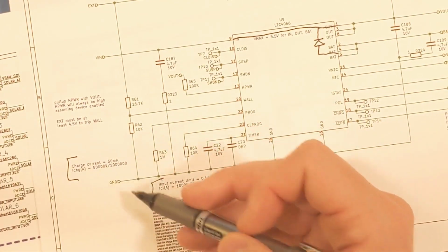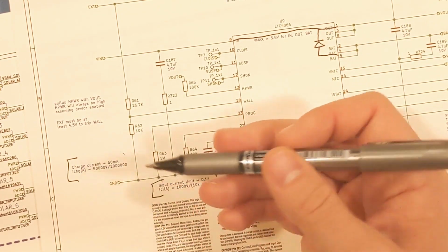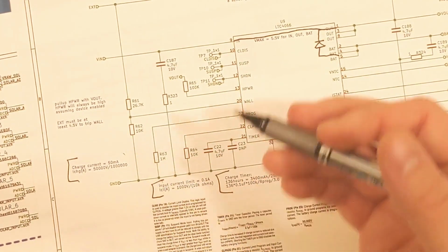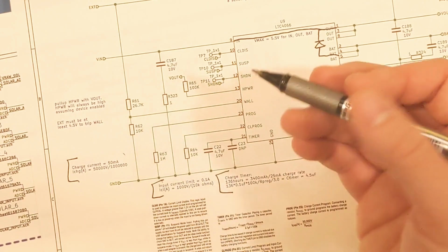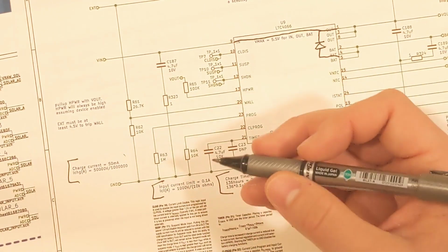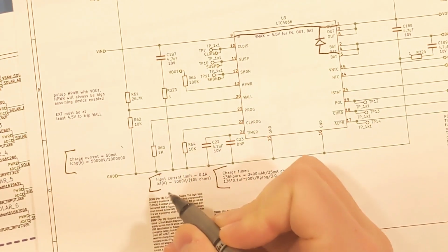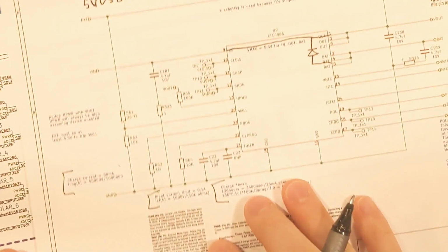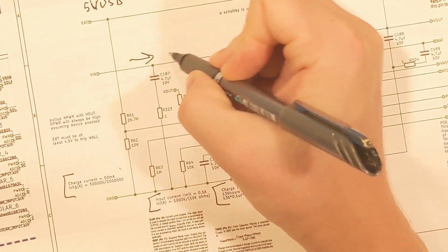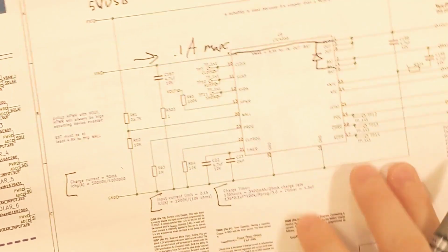The reason I set the charge current to only 50 milliamps is because the solar cells might only output 200 milliamps, and there are 2 of these chargers. So if both of them are going, that's 0.1 amps, and I wanted to have some margin because we might not always be getting optimal conditions from the solar cells. Also, the input current itself is only 0.1 amps. That means from Vin itself, only 0.1 A max will ever come through.